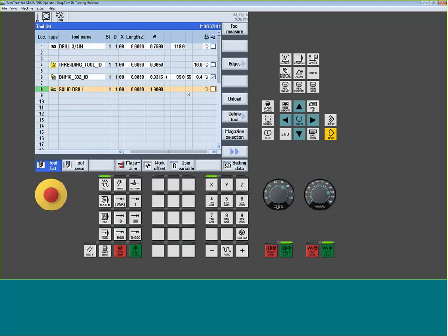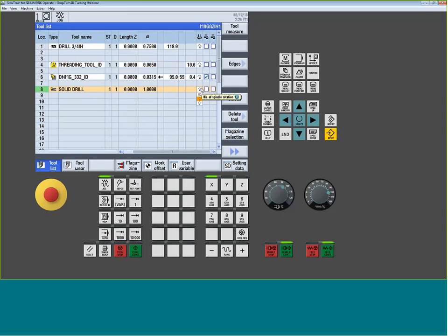But what I'm talking about as far as the static or the live, if you think about the direction from the spindle scenario, it's opposite of the main spindle. So it's very common to find that you have to change your spindle direction here. Now, I've seen some builders where on a standard lathe, you always have to invert the static drills. I've seen other builders where they have this set up so it matches the main, but you have to flip the direction if you have live tools.